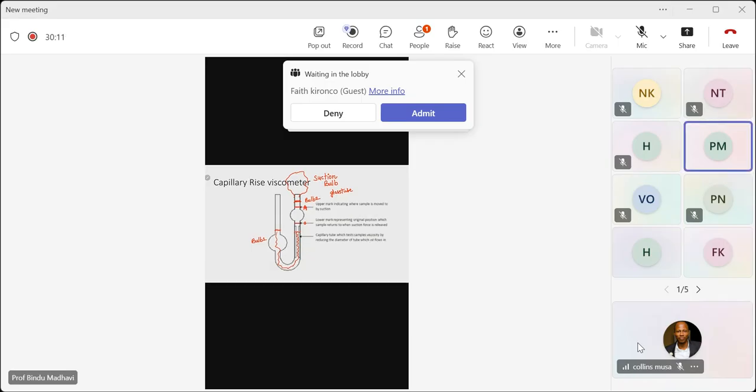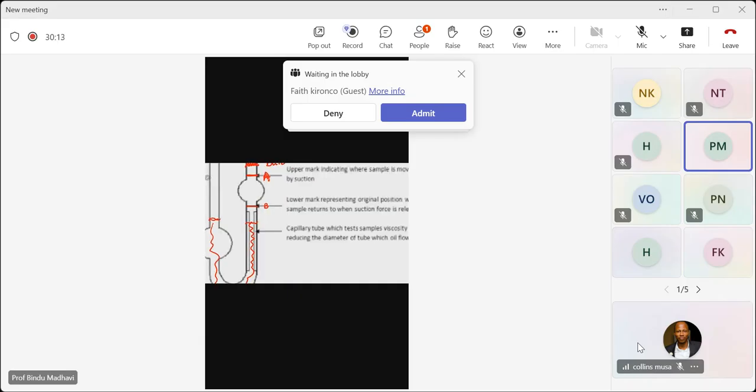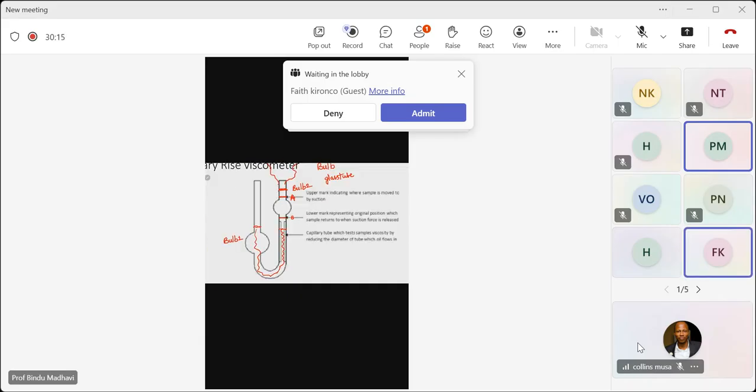So this is called level A. Now we made the liquid come slightly above level A. If we don't apply this vacuum, the level will not rise in the second arm. So to raise the liquid above level A, we apply suction using the vacuum pump.